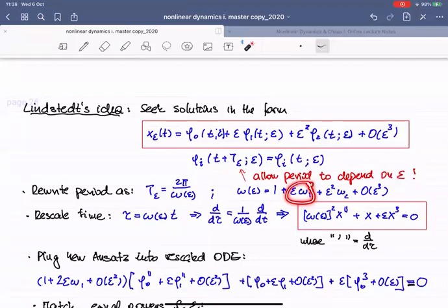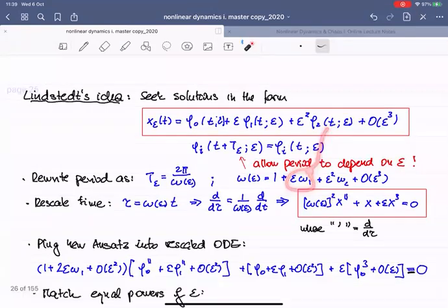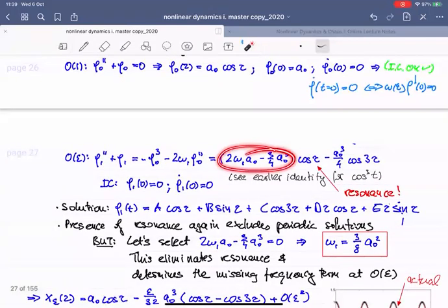And now comes the conclusion that, wow, I get precisely the first order approximation of the periodic solution, if for that choice of omega 1, this term cancels out. So I make this 0. And when I solve this for 0, it gives me an equation for omega 1 as a function of a naught, which makes sense because my initial amplitude will influence my first order correction to the linear frequency. So the nonlinear change in the frequency will depend on the amplitude order.